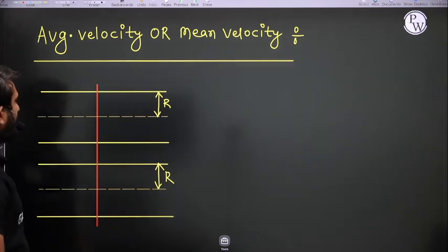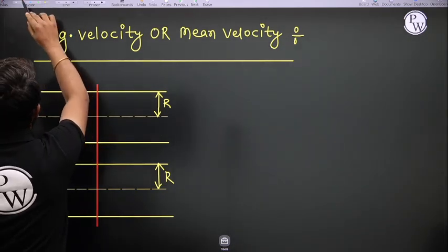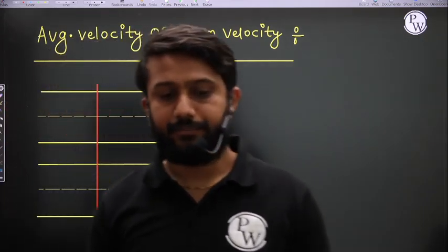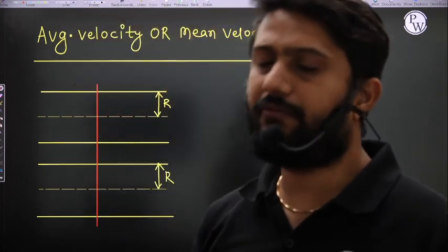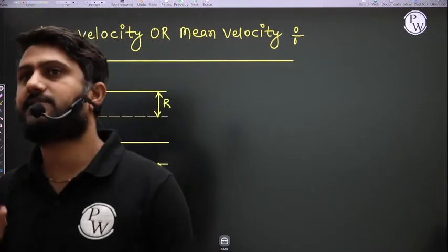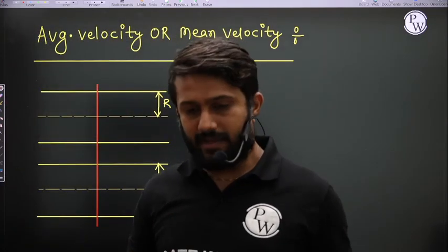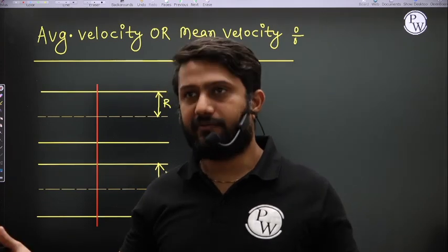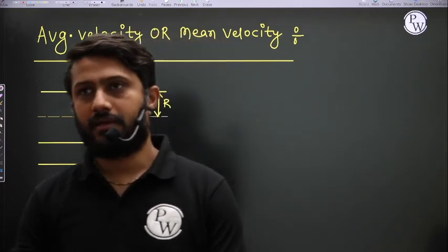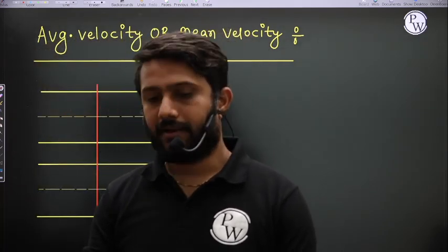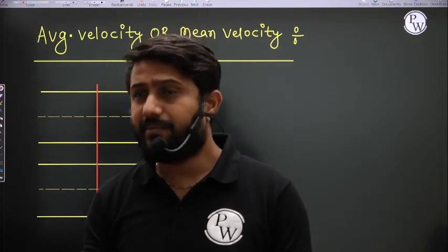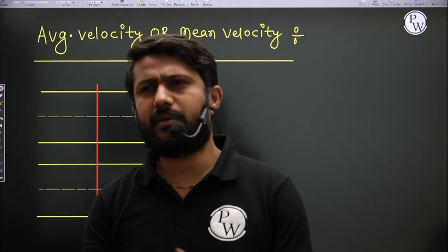So we know that at a particular section, velocity, right? And see one thing, we are mainly focused on the developed region, because the developing region is very small. If you consider a long pipe, let us assume a pipe of 5 meter length, the entrance length may be 10 centimeter, maybe 20 centimeter, maybe 5 centimeter.